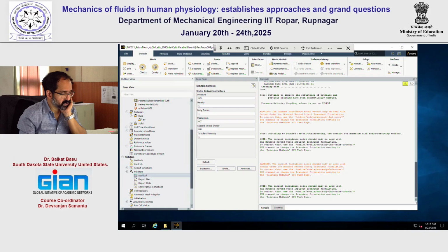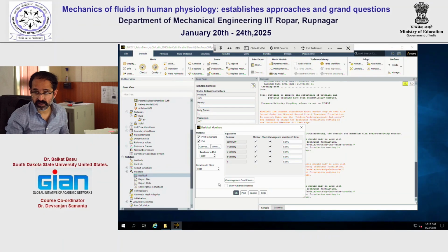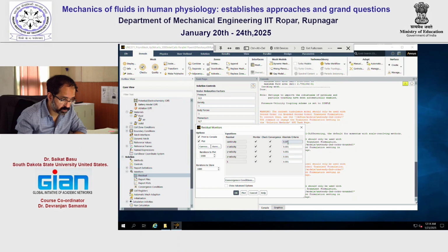and the residuals. So now you have to figure out the residuals for the proper convergence, and for that as well you need to look at literature to figure out what is the accepted standard. So for the continuity residual, we are going to use. Could you guys open up the protocol? I don't think it's 10 to the power of minus 6.